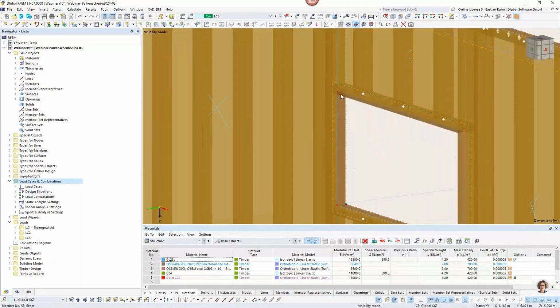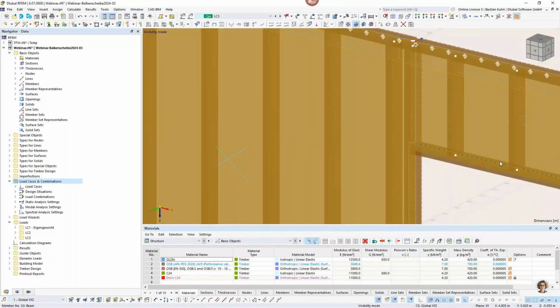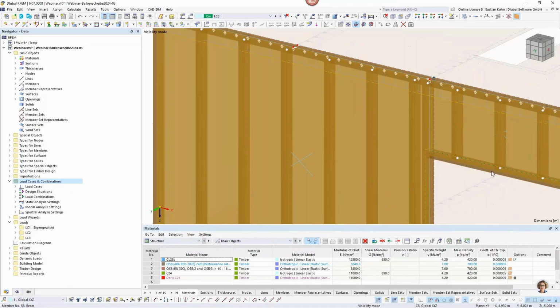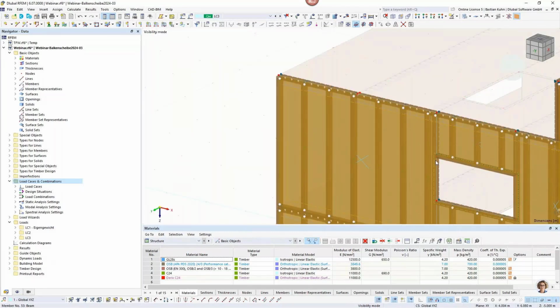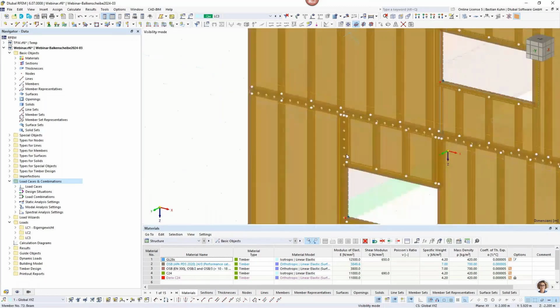What we do here in Europe is that we are using the top beam, or however you call it, on this window, and move it to the next stud. That's one of the possible constructions, and then it's completely shear stiff, and of course it's nailed on every part wherever our OSB plates are connected or coming together, and there's always a beam or a post behind it. That's where it can be nailed on. That's for sure.